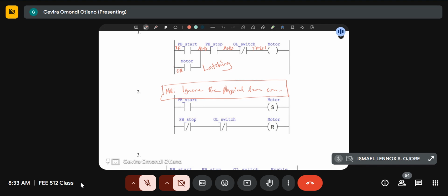So in this case, if it was not stated, then maybe one, you would state that we need to have these as normally open contacts. That's number one. Number two, we need to connect them in parallel rather than in series. We need to branch them out. I don't like the words parallel and series because they confuse me with circuit theory and all that stuff. So in PLC, I say we need to branch them out, meaning we connect them in the logical OR fashion rather than the logical AND fashion. Okay, so that's basically it.